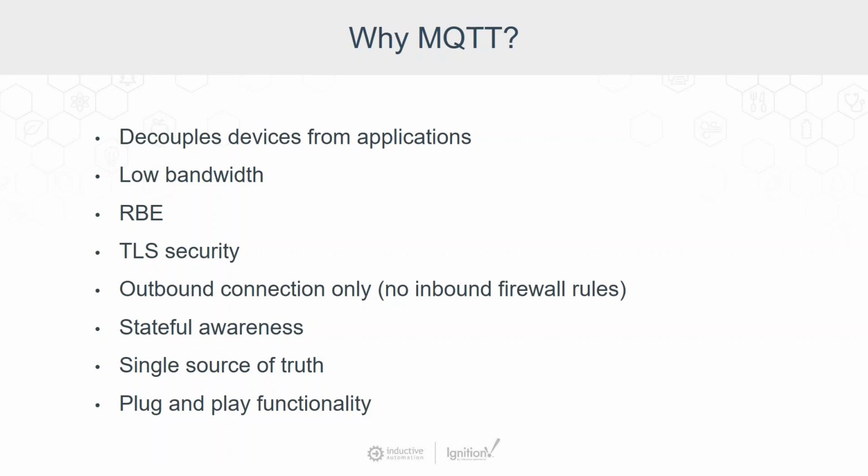This is probably one of the most important things, because if we're in a SCADA system, we have to know that we can trust the values that are on the screens. That we know the quality, we know the state of the connection to that PLC all the way through. And while the protocol decouples everything, the applications and the devices understand this connection, understand this state, and guarantees that we know what's going on.